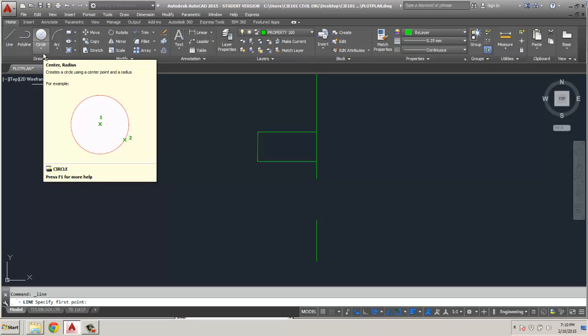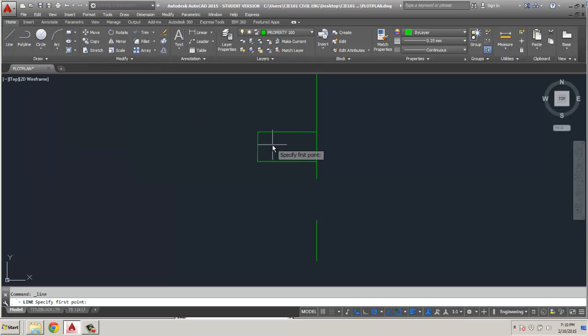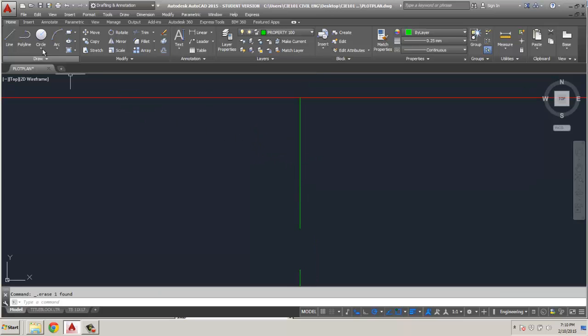All right, if you look at figure 10.12.1, I think there's a little bit of a misprint in the book there, so I'm going to delete this. I'm going to follow the written instructions rather than going by the textbook. So I'm going to start up here, and we're going to go down a distance of 212 feet, 7.1 inches. Now it says, south of northwest corner, then south.